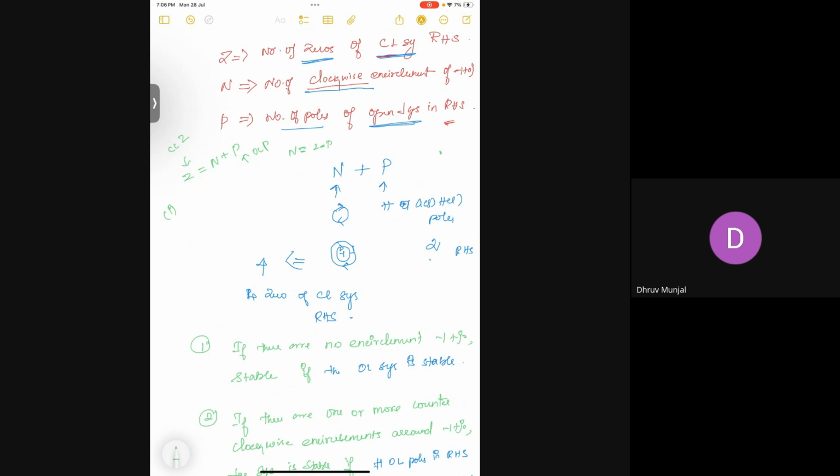But let me do it from our point of view, whatever we have learned so far, and you see whether it answers your question. In the first question, the plot has encircled -1 two times in the clockwise direction: the inner circle is clockwise, and the outer circle is also clockwise.